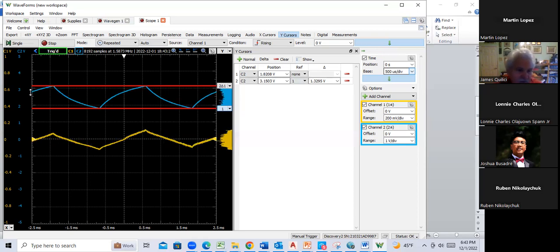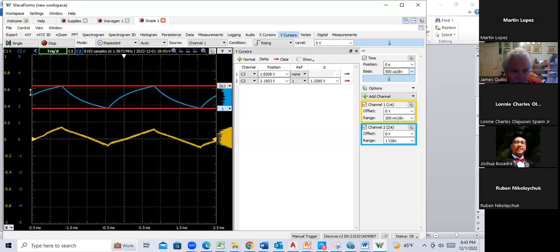Those are the first two things to check. If your circuit isn't working, try to figure out if your base voltage isn't where you thought it should be, or your collector voltage isn't where you thought it should be. Try to figure out what's going on in those two places. That's a good place to start. The collector voltage is always a good place to start.